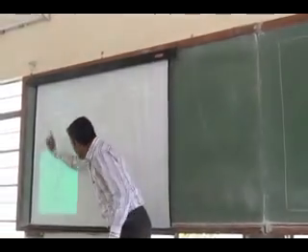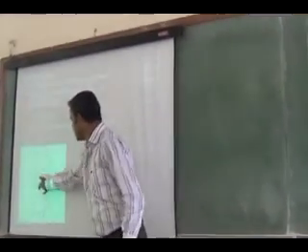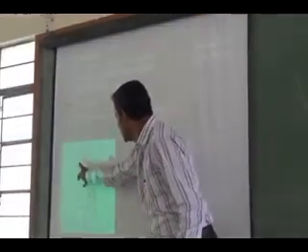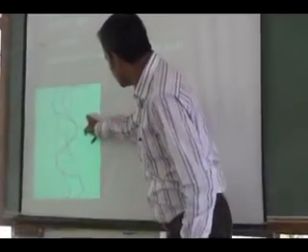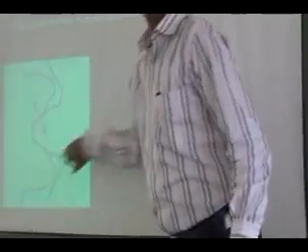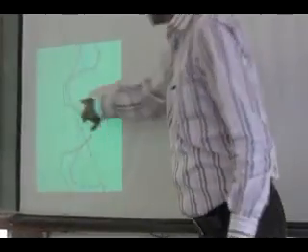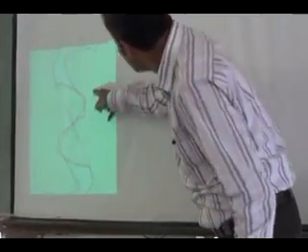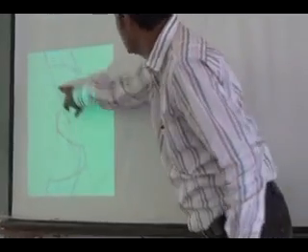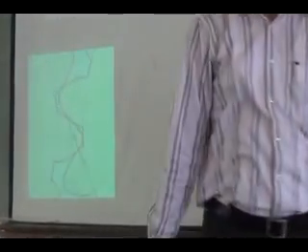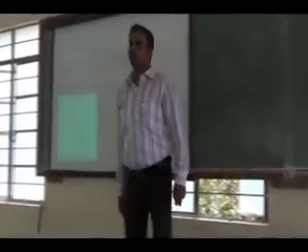You can see the point of contact of these two gears moving like this. How is the point of contact moving? It is moving along a cycloidal or involute path. The point of contact moves along an involute path and it ends here. At the same time, another gear tooth comes and makes contact. That's the point of contact.